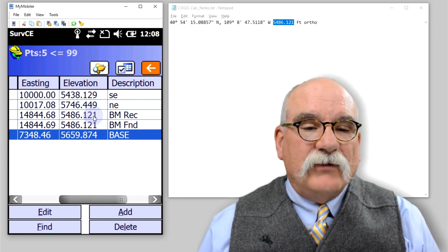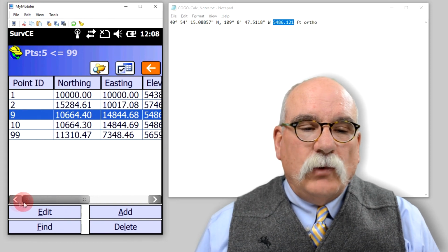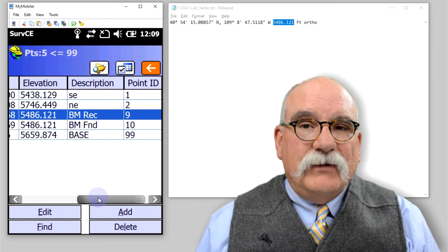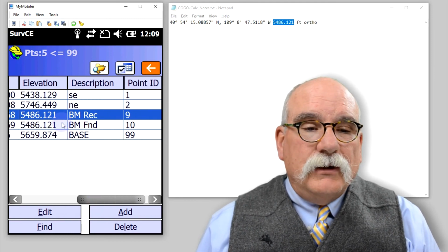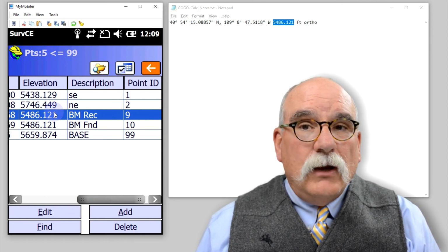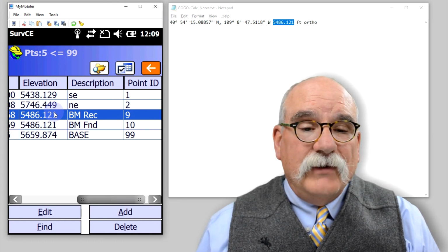So when you reprocess the raw file, it doesn't matter what you do, the coordinates for this point number 9, which were derived in the calculator, will not have any raw data, so they won't change. So all of these points have been moved appropriately in elevation. We're still using an LDP. All we've done is tied into a good elevation.